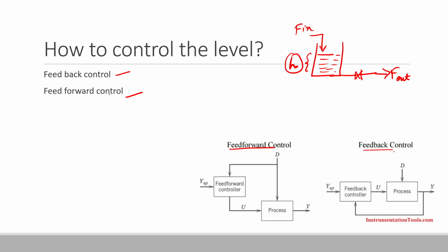For the first approach that we discussed, in order to control the height of the tank, we can directly measure the level of the tank, and on the basis of this we can control the outlet valve. That's basically, if the level increases, then we can open this valve and let the water flow out, so the level in the tank will be controlled.